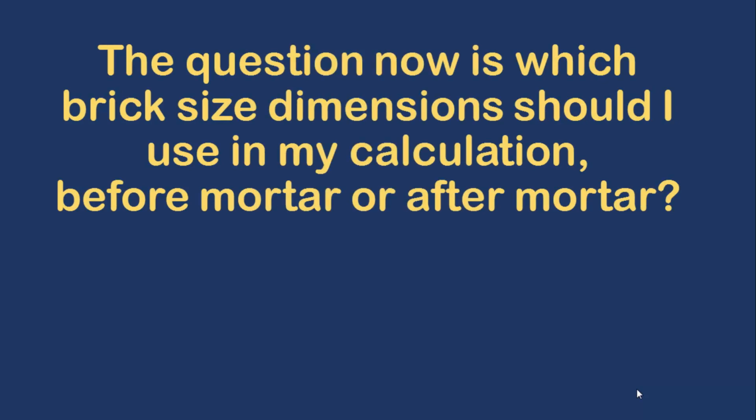The question now is, which brick size dimension should I use in my calculation, before mortar or after mortar? Take 5 seconds to think about this question and try to answer it. The answer is after mortar, because the size after mortar represents the reality of the wall and how it is built.